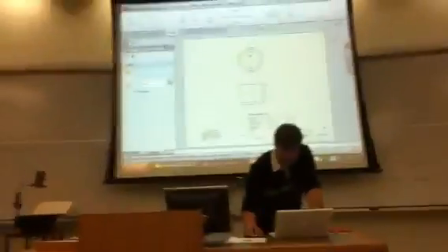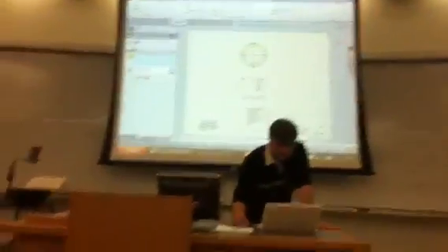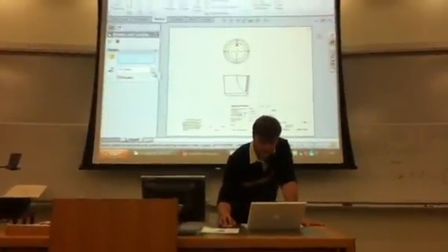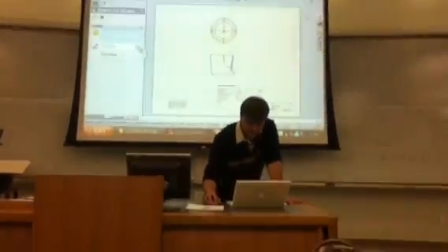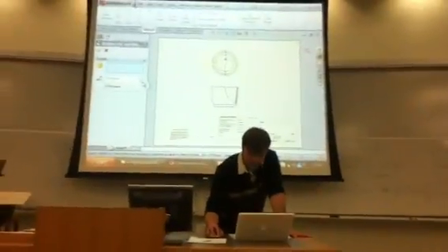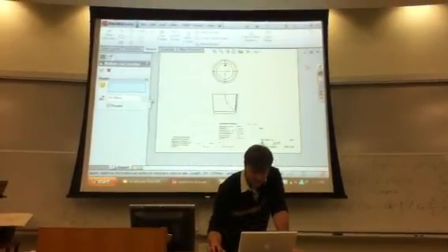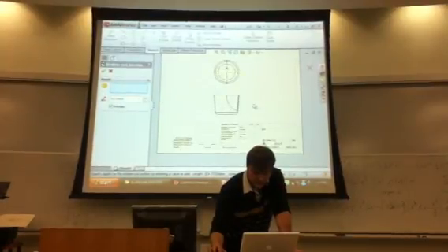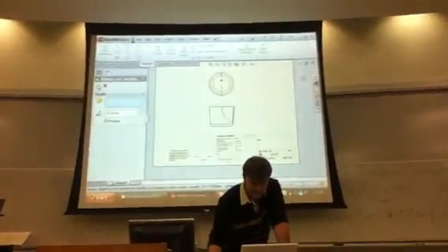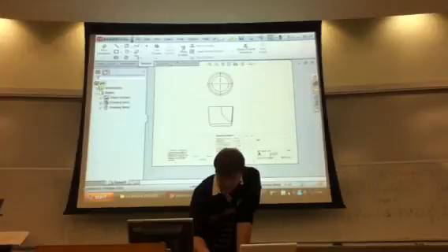You can see as I increase the number of millimeters that we break out the section, on the bottom drawing you can see it cutting through as well. So let's put it in the middle, and if it's at the middle, we can get a good representation of what the thickness is supposed to be. So 60, 50, 50. So now we have a nice little broken out section view.